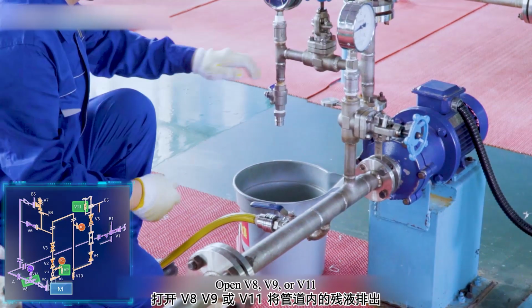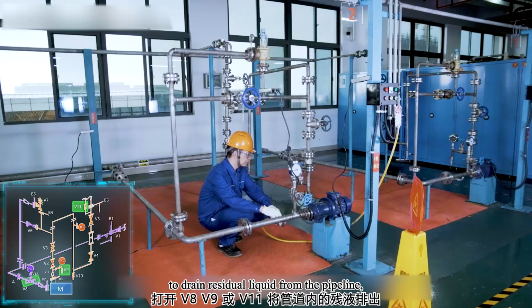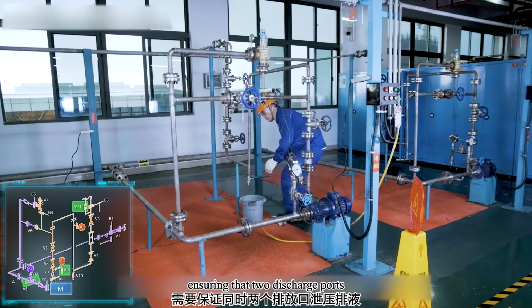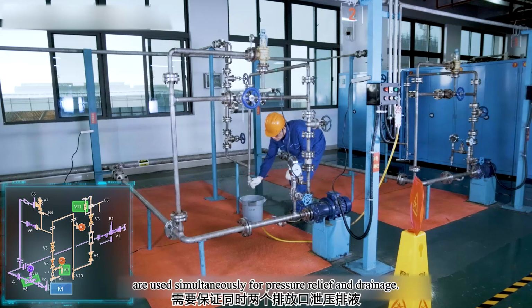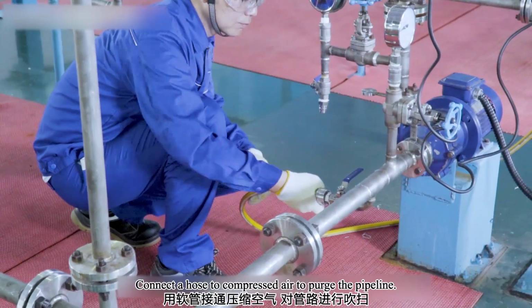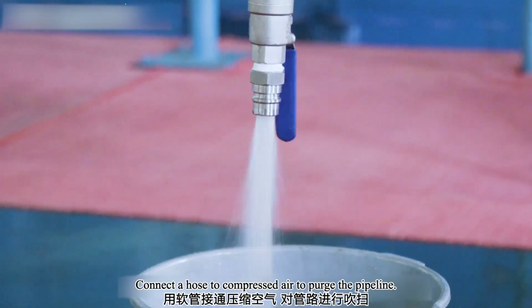Open V8, V9, or V11 to drain residual liquid from the pipeline, ensuring that 2 discharge ports are used simultaneously for pressure relief and drainage. Fourth, purge. Connect the hose to compressed air to purge the pipeline.